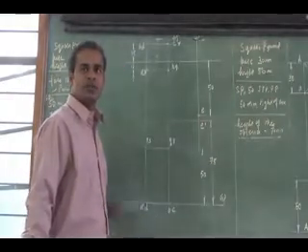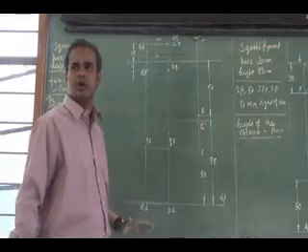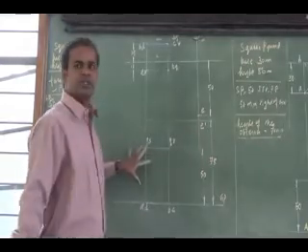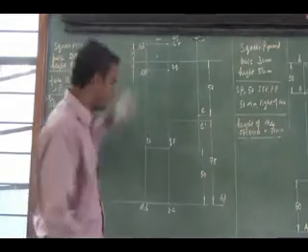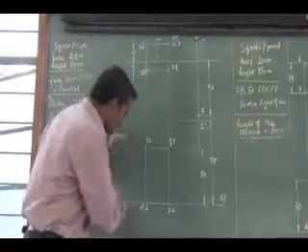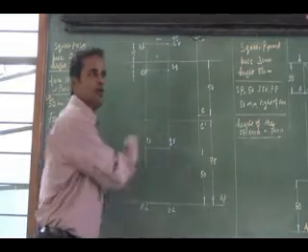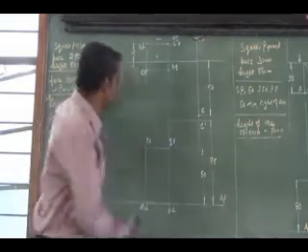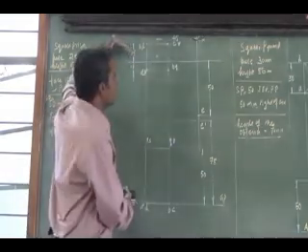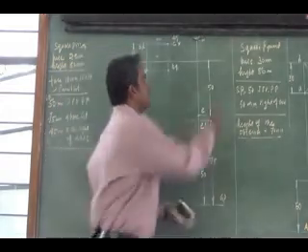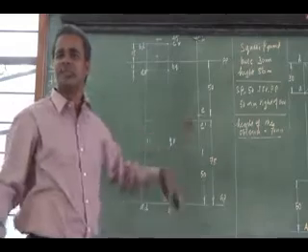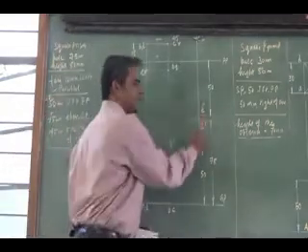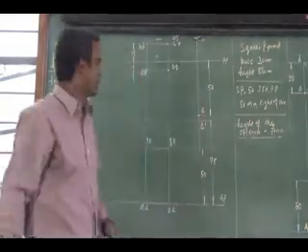Don't draw the ground plane to the bottom, similar to the previous problem. Since the perspective view you are going to obtain for this in front of portion will be bigger in size, I need a space below the ground plane. That's why I am leaving a gap. But you maintain the gap between the picture plane and the ground plane that is more than the above and in front of distance of the station point, because E and E dash should not interfere.